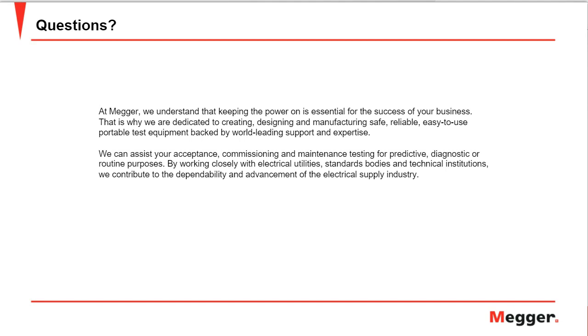When we talk about power swing, be it stable swing or unstable swing, a few functions for sure get affected, like instantaneous phase overcurrent relays. If the line current during the swing exceeds the pickup setting of the relay, then the instantaneous overcurrent relay will operate during the out of step condition, or the unstable power swing condition.